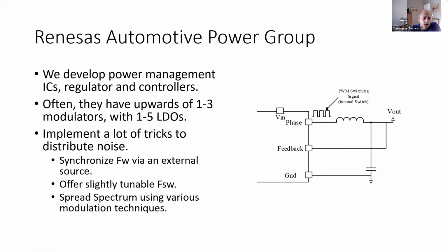We synchronize our, that should be FSW, our switching frequency, to an external source. So you can feed in PWM to kind of change this within limits. We offer slightly tunable switching frequencies. And then the one thing that everyone has heard about is we offer spread spectrum, that's a hard word to say, using various modulation techniques. I won't go into it. Some of them I understand, some of them I don't. I wrote an article about it in Compliance a little while back.